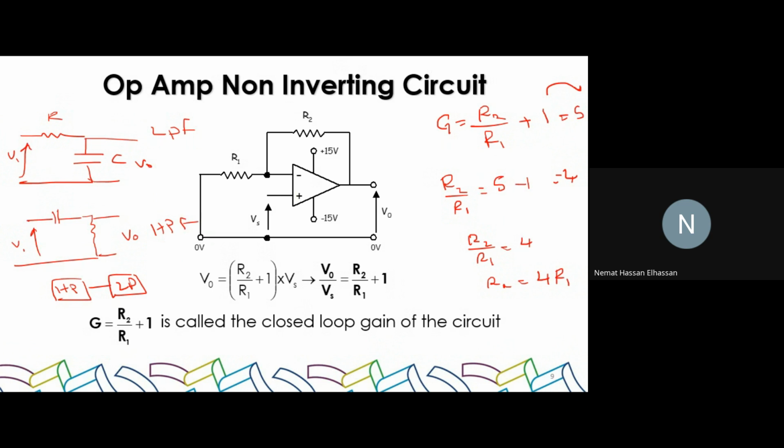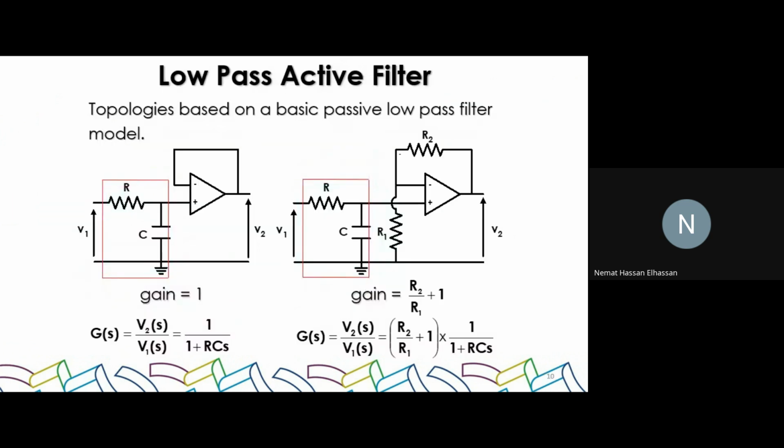They don't add gain. So if I want to create an active filter, one of the simplest ways to do it is take this passive low pass filter, for example, and connect it in series with this amplifier circuit. Simply take an amplifier and connect it to the output of the filter. This makes an active filter. Now, before we move on, what type of amplifier do we have here? Is it inverting or non-inverting? Where is the input of the amplifier connected to?